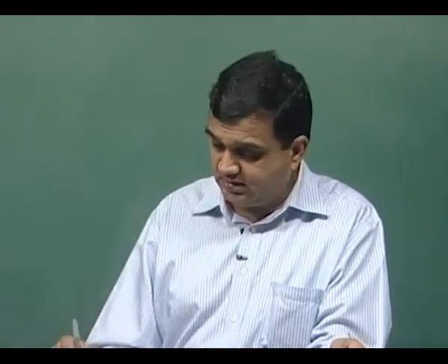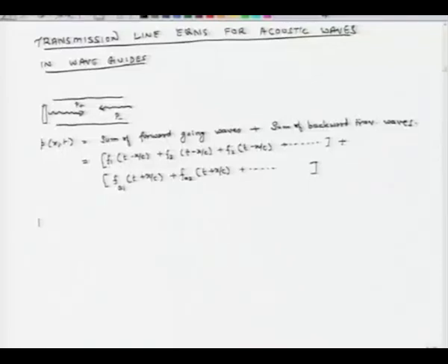So, in that case I can rewrite this equation as p(x,t) is nothing but the real part of P plus(s) e^(st - x/c), and please remember that s is a complex frequency here.